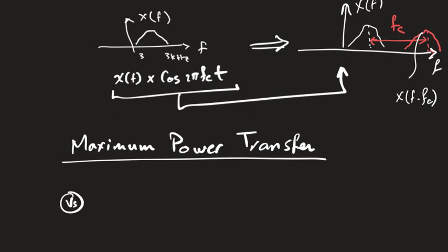So if you have a certain voltage source, typically this voltage source comes, whether you like it or not, with some non-idealities, so it has some internal resistance, right? It's not pure without an internal resistance, right? Those two components, the value of the voltage source and the internal resistance, are things that come with the equipment. You buy the equipment, this is a 5 volt source, an adapter for example, and someone has measured its internal impedance due to the design and found it to be, for example, 5 ohm, 6 ohm, 10 ohm, whatever, okay? So this is something that you don't control.